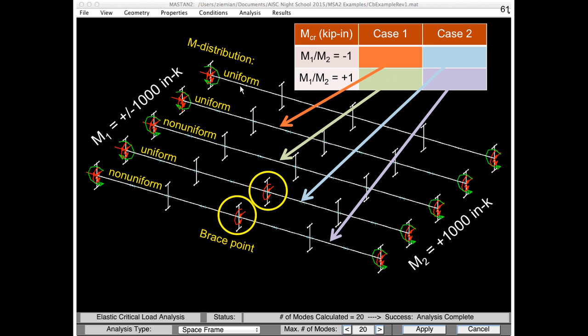So this beam could never be manufactured, but it literally has no resistance to cross-flange bending. All right, so the only resistance in the torsion term is GJ. It has no C sub W. And then what I wanted to just show you for fun is what the impact of just turning on the